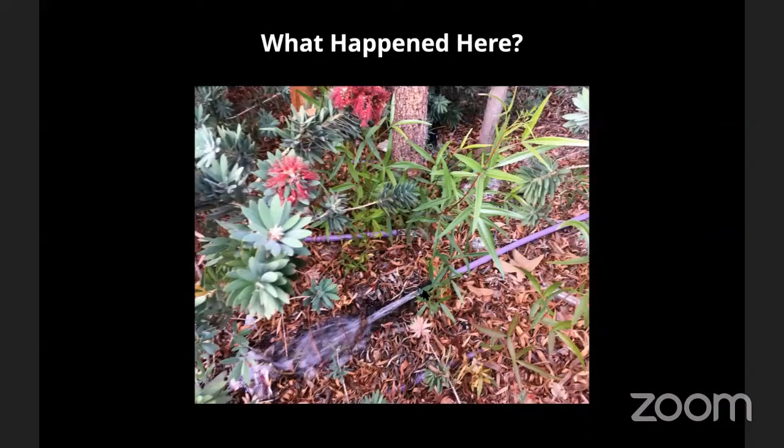Here is a case where that compression fitting, which I mentioned that I don't like as much as the barb fitting because over time it breaks. This is exactly what happens when the compression fitting comes apart and then water's just shooting out. And anything that was going to be getting drip irrigation from this side is not getting anything. So pretty important. And even with this, we've had this happen in our garden because the original contractor did use some of these for the installation. And sometimes it takes a surprising amount of time to find this.